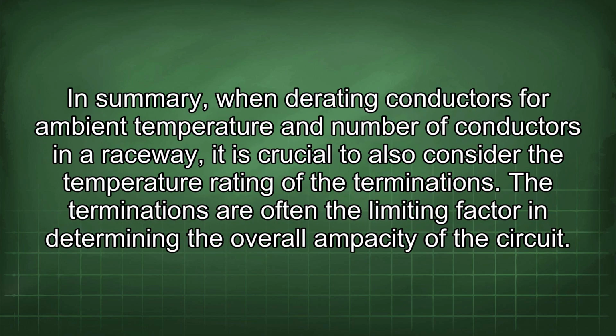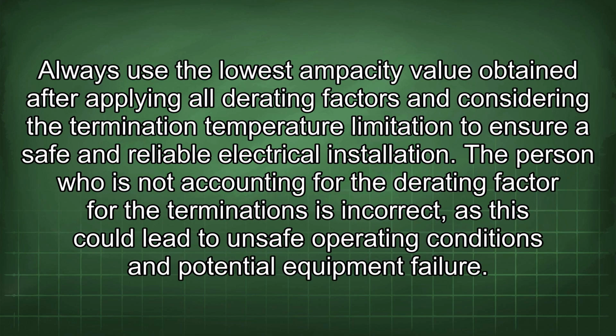In summary, when derating conductors for ambient temperature and number of conductors in a raceway, it is crucial to also consider the temperature rating of the terminations. The terminations are often the limiting factor in determining the overall ampacity of the circuit. Always use the lowest ampacity value obtained after applying all derating factors and considering the termination temperature limitation to ensure a safe and reliable electrical installation.